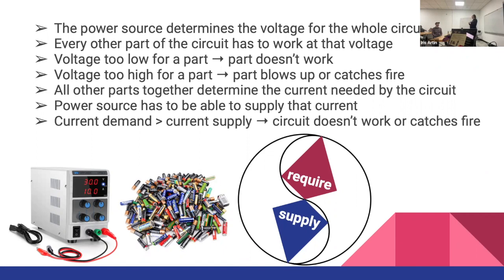If you give something not enough voltage, it usually just doesn't work. But sometimes if you give it not enough, or almost enough, it will just be kind of flaky. And so if your circuit is being flaky, one of the things you can look at is whether the voltages are actually compatible in the things that you're doing. This is one of the reasons why I think it's really important when you're just starting to follow tutorials that were written by people who know what they're doing, because that kind of tutorial is going to have the right choice of parts that actually work together.